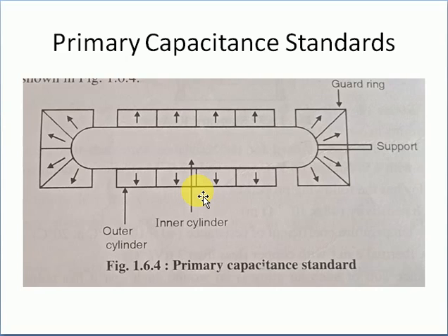Air as a dielectric material possesses certain disadvantages, such as low dielectric strength compared with solid dielectrics, and therefore a capacitor using air as the dielectric requires a larger size. So suitable spacers using solid dielectric can be used with appropriate consideration. Air capacitors have extremely low loss, and insulating material used in such capacitors has to be placed in a region of low field strength. The breakdown strength of gases increases with their pressure, but the dielectric constant remains normally unaffected.